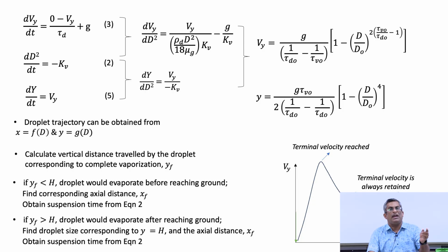But if we account for that, for example here, so this is the d square law. So earlier we considered this term as 1, which means pure diffusion. So the Sherwood number, if you put Reynolds number equal to 0, is 2, so here you don't have any effect. So we assumed that the Reynolds number is 0, but the Reynolds number is not 0, because always you have some finite relative velocity between the particle and the flow.